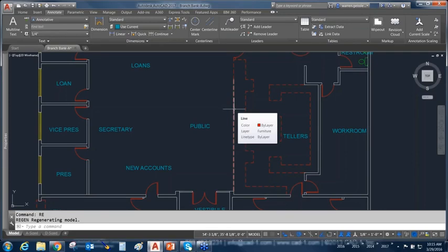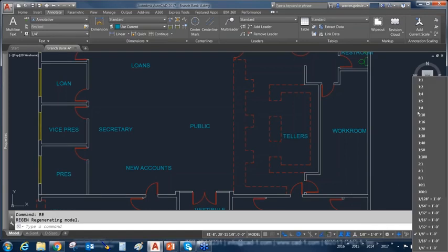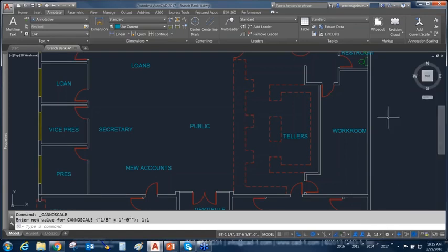Now, how is that controlled in model space? In paper space, we set it on a viewport by viewport basis. In model space, you do the same thing fundamentally. I've got one model space viewport, and I set my plot scale down here in the ribbon, about the same spot that you would set it in paper space. So this is where I would control how I think I'm going to print it or how I want to see my line types. Now this is important because this scale factor is going to get applied to all of my annotation here in a moment. The line types are the first part. The line types are very, very easy, and I can set the line types up and change those.